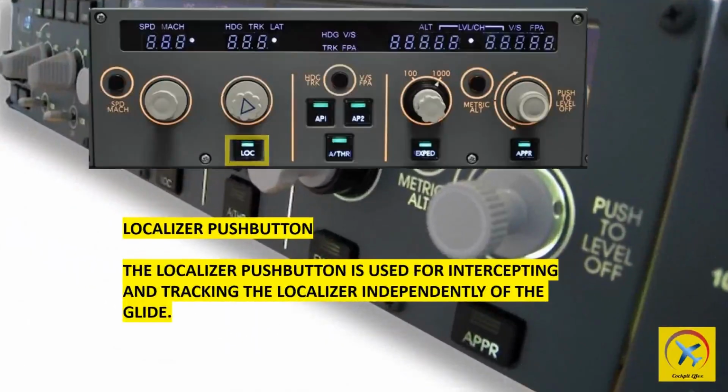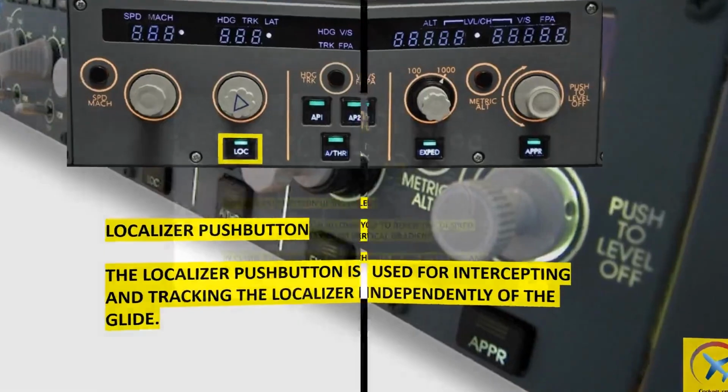The localizer button arms, engages, or disengages the localizer mode. It illuminates the managed lateral light. Dashes appear in the heading or track window when localizer engages. It takes a minimum of 3 seconds after arming for the localizer to arm.